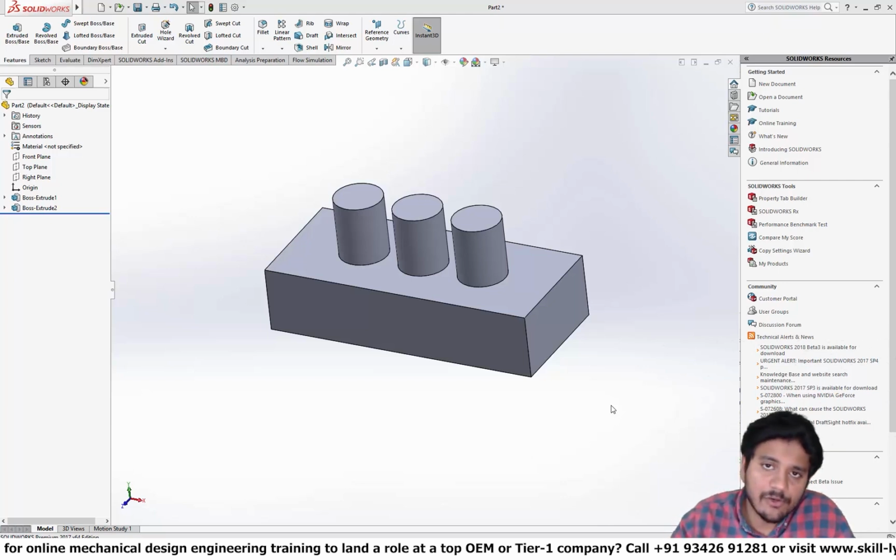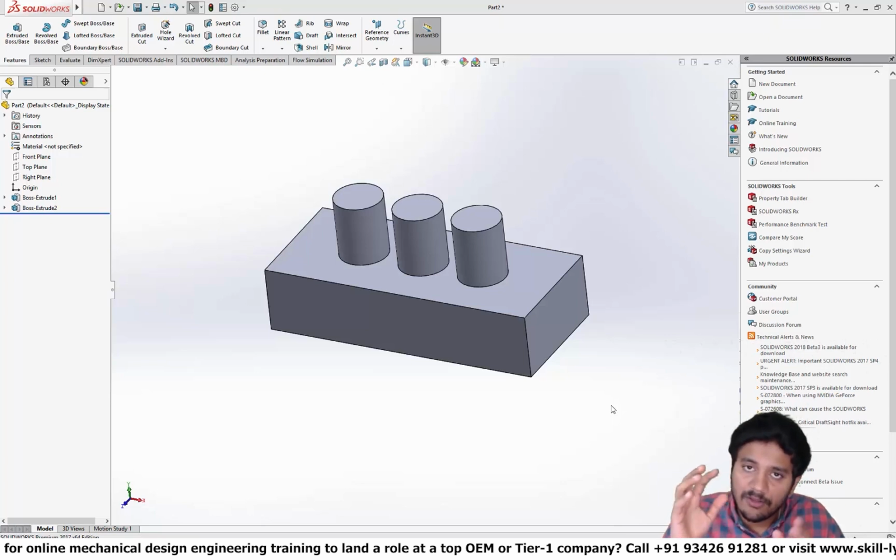So in this video, we are going to be learning something called boundary flagging. So the whole idea is when your geometry is represented as a bunch of triangles, you need to group these triangles into meaningful boundaries. And once you have done them, you can use these boundaries to create volumetric regions, and you can also use these boundaries to specify the required boundary conditions.